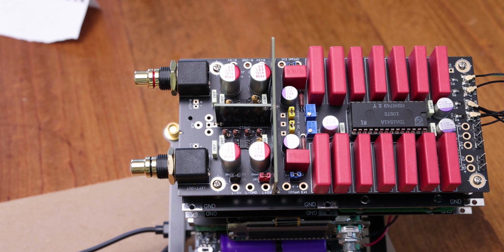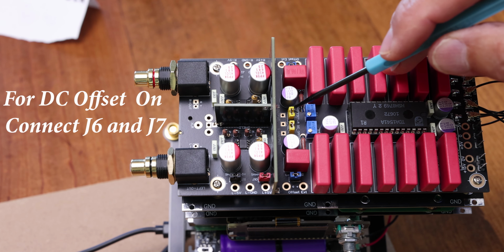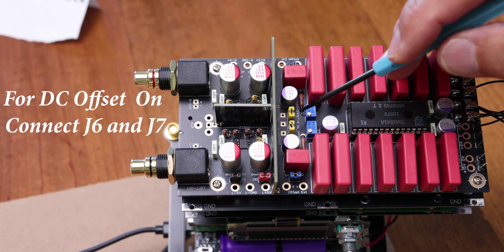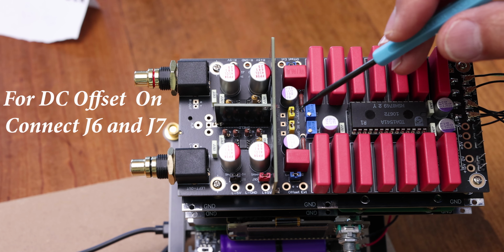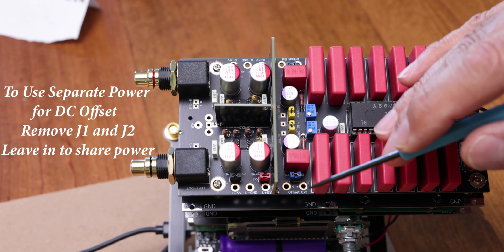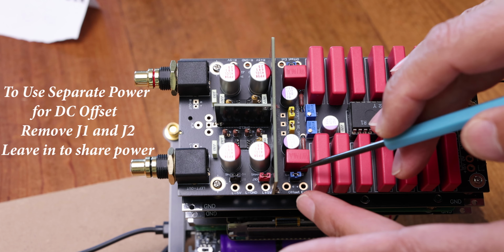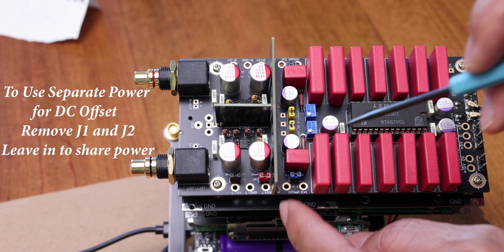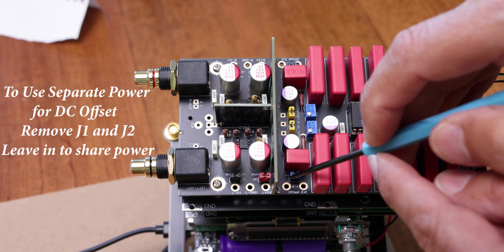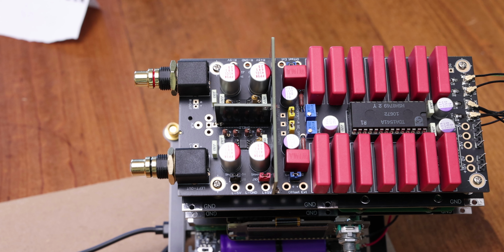Now, configuring all the jumpers, what do all the jumpers do? So let's start with these jumpers here. Those two here are if you want DC offset or not. If you don't want DC offset, you can take them off. This is in case you want to use a capacitor instead. This is J1 and J2. Basically, if you want to provide your own power for the DC offset, you don't want to use the 5 volt that's coming on the board, you can pull those jumpers out and provide your own 5 volt power, either for both of them together or each one of them separately.